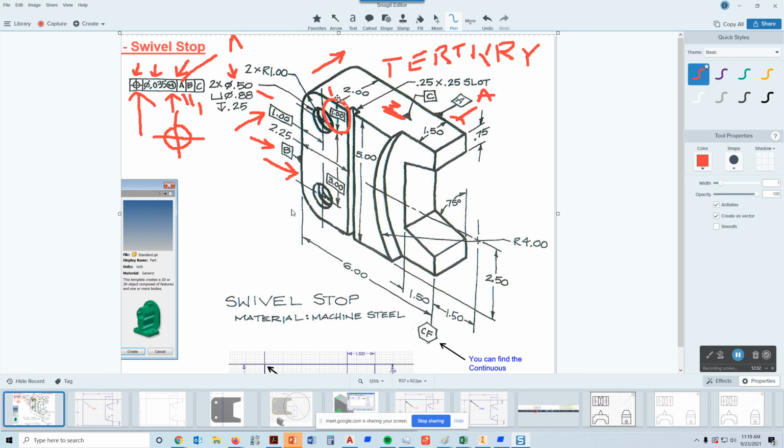Now the hole doesn't have to be perfect, but the center axis of the hole has to run through that 0.035 cylinder that we see right over here. And so that's what the tolerance is for the hole. The hole can rattle around inside that 0.035 millimeter diameter cylinder, okay? So I know that's a lot to put together into one feature control frame, but if you can explain that, it's very powerful.